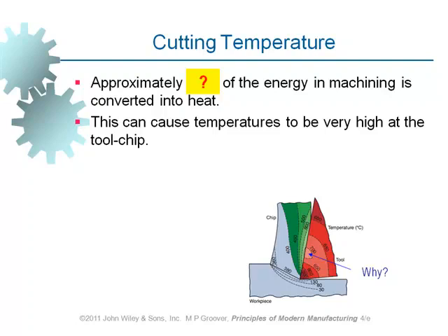It is important. Not just that, there is a relationship between the life of the cutting tool and the temperature. As the temperature of the operation increases, the lifetime of the cutting tool decreases. So increased temperature of the machining operation increases your cost of tooling, which is undesirable. What else? I have mentioned 2 reasons so far; if there are other reasons, let's add them to the agenda.